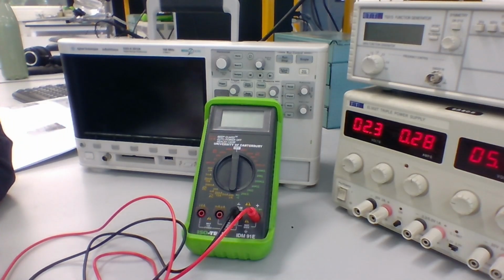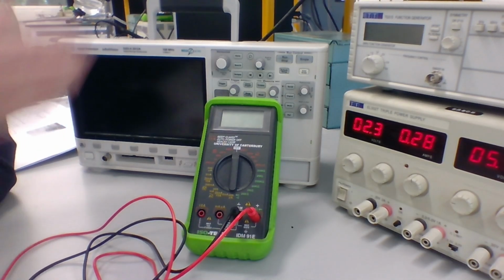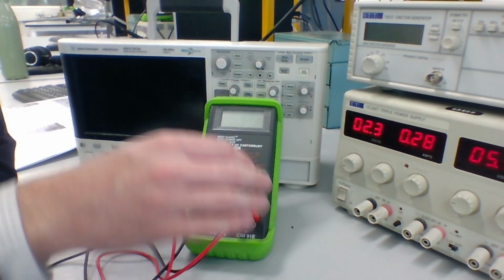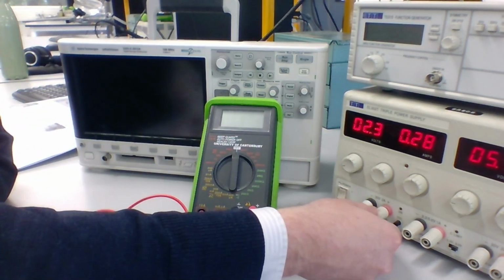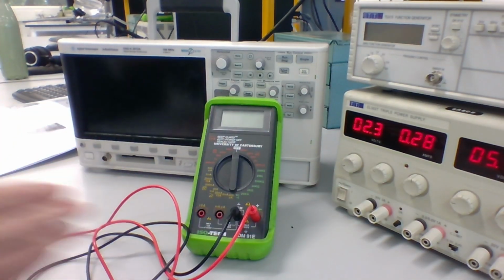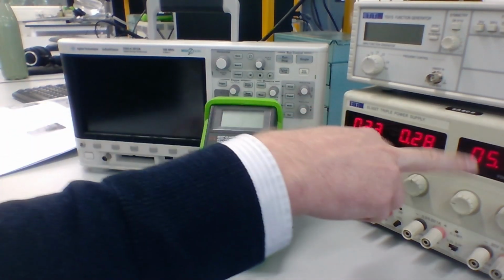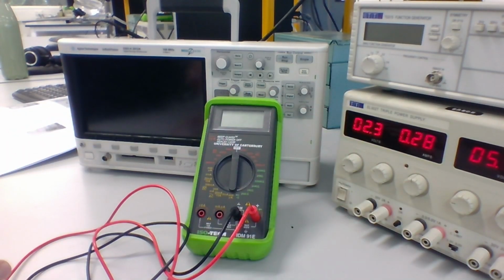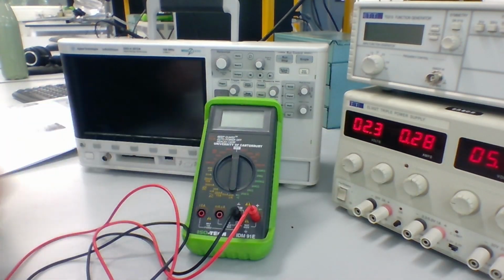For this lab, we're only going to use a single side of this power supply, so I'm only going to show one of those. It doesn't matter which side you use if you're using a single power supply, they're both equivalent. Different power supplies will behave differently. This has two independent power supplies. Other ones will let you do what's called slaving them together in series or parallel so that you can get higher voltages or currents. But these are two independent power supplies.